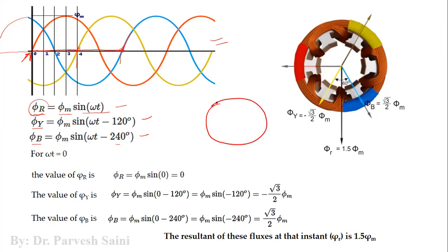For example, this is the stator part, right? This stator has three phase winding, right? So this three phase winding produces a three phase flux which is rotating in the air gap. And then we have a rotor here. This rotor has some conductors. The construction of rotor could be a cage type construction or wound rotor type construction. Fine. So when this flux rotates in the air gap, it cuts these conductors.